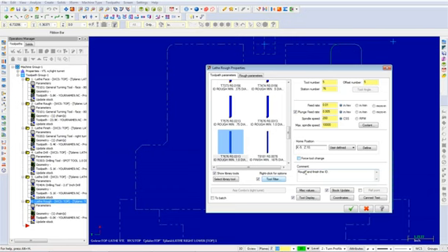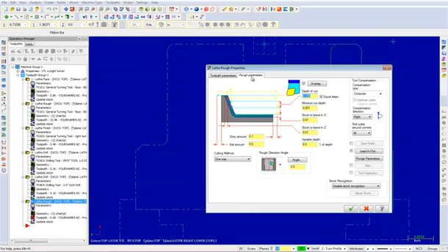Now select the Rough Parameters tab and make any changes as shown. Change the stock recognition to Use Stock for outer boundary. Ensure that the depth of cut is set to 0.125 and the amount of stock to leave in X and Z is both 0.01. You can now select the OK button to exit the Lathe Rough dialog box.